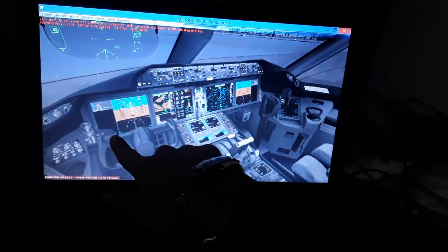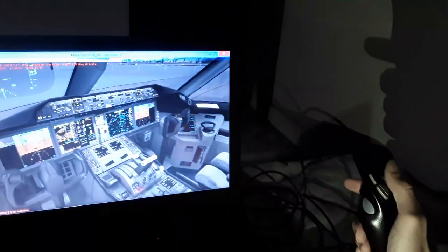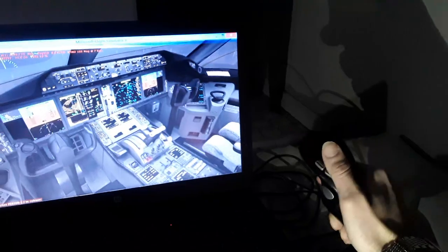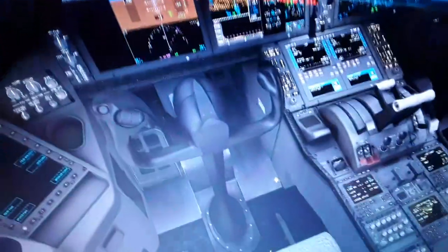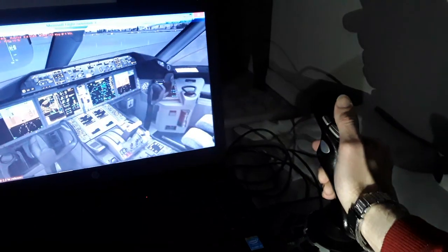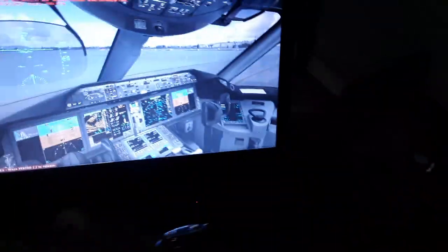We have the horizontal stabilizer, also the switch here for trimming the horizontal tail for extra balance in flight. So you make turns using the aileron and spoilers, and also we have the rudder pedals down here. You can see the rudder pedals. We can make left and right turns, yawing turns in flight, also using the vertical tail, the rudder.